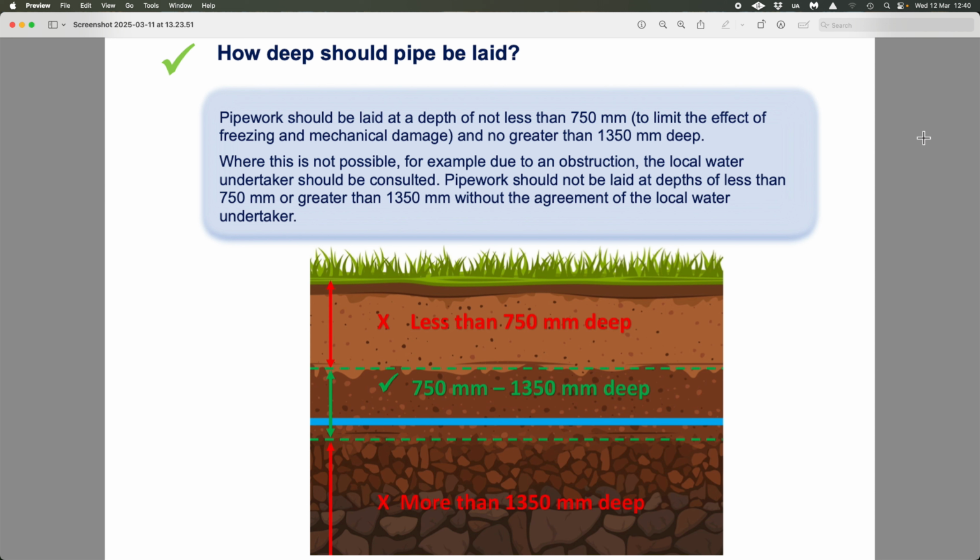And that is the sort of thing that I want to avoid. We're engineers. We want to try and just keep the system running nice and smooth, nice and easy, and no dramas to anything. Now, you can obviously buy things like shock arresters and that sort of thing to put on combination boilers or cold main systems or whatever it is, to stop that initial bang when you turn a tap on or something along those lines. So that's that point, and I'll come on to the next slide now.